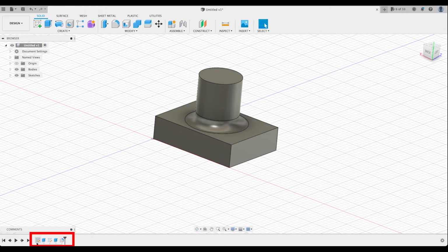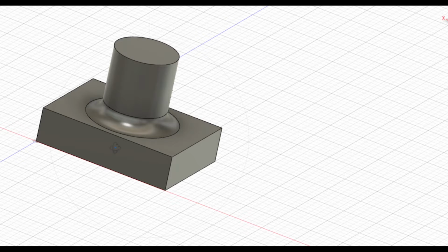And again, if you look down on the timeline, we've gone drawing, extrusion, fillet. So we can also fillet these edges here to make the rectangle less hard edged. So I'm going to press F again, and I want you to look at this particular feature. Let's see if I can just orient this to make this a little bit more visible. So we know that there's a vertices at the back here, and we can see these three.